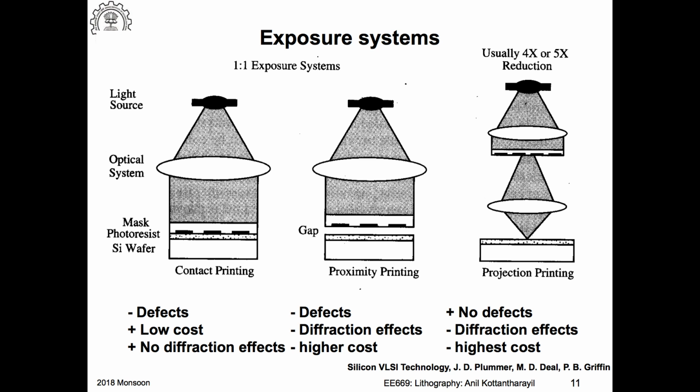But there is some problem with defects, because photoresists are usually soft materials. It's usually a highly viscous liquid, and you are annealing this at 100 degrees centigrade and so on, and most photoresist can very easily be removed using organic solvents. So it's a soft material, and it can actually stick to your mask. That is called defects on the mask.